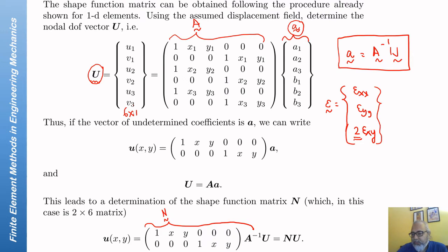We add this 2 for the shear strain, and we solve for only these 3 components of strain and the corresponding components of stress, because there can be one more component of strain or stress, depending on plane stress or plane strain, that is still required, but that component will be dependent on the in-plane components of strain or stress, as the case may be.